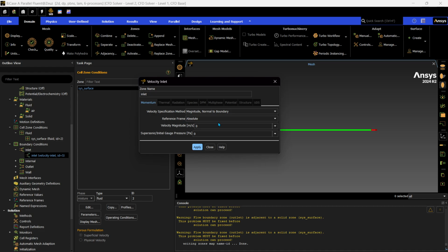You could use any target you want, but I find that with air, a Reynolds number of 250 would be best for your Couette flow. And even though we're doing Poiseuille, I want to keep my Reynolds number consistent with all the different cases. So we're going to be doing the Reynolds number of 250.